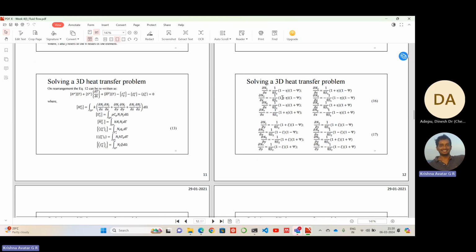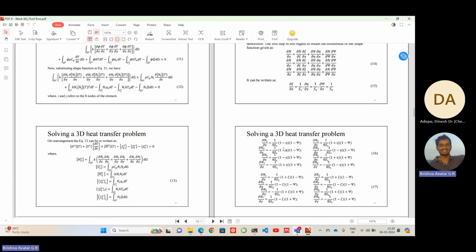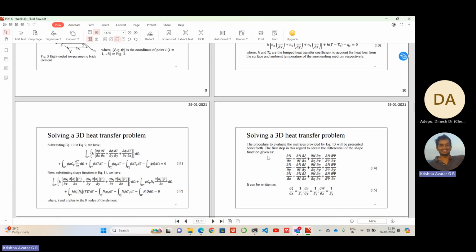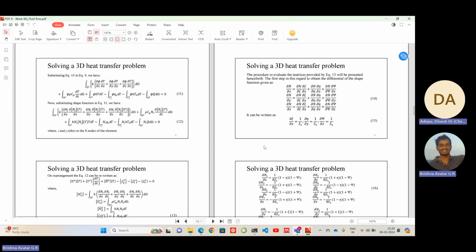So it's like we are just multiplying those. If you want the first shape function for 3D, then we will multiply three shape functions for the 1D case. We compose the shape function using the direction along x, along y, and along z. Then we multiply all of them, and at the node point at which it is defined, it's like 1 into 1 into 1.